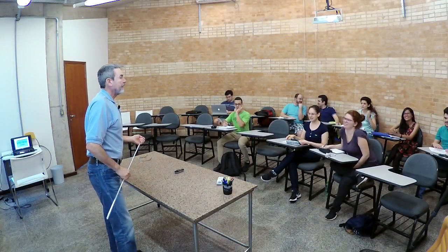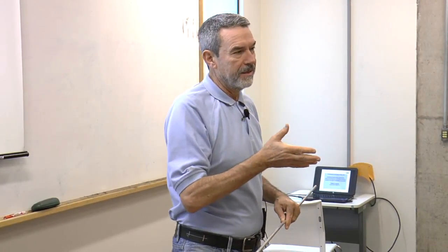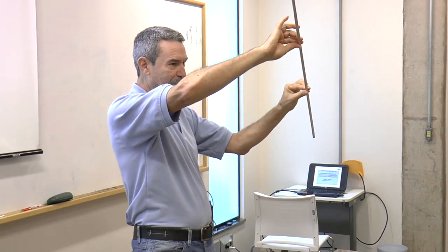Good morning. We are going to continue the class about nucleation in supercooled liquids. Sometimes we talk about crystal nucleation or crystal growth or crystallization in glasses. Actually, we always deal with supercooled liquids because even if you're working below Tg, remember that the glass will relax to the supercooled liquid state and then will crystallize.